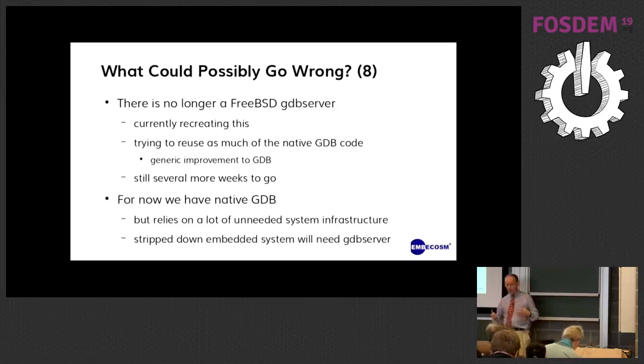And that's why, for embedded systems, you have a program called GDB Server. GDB Server runs on Linux, and it runs on LynxOS, and it runs on one or two other things. And it used to run on FreeBSD, but no one's run GDB Server on FreeBSD for a long time. When you run GDB Server, that small little program, which doesn't need much operating system resource, runs on your target, and you connect via a serial line or TCP/IP to GDB proper running on a workstation somewhere else. That's the standard way to debug an embedded system.